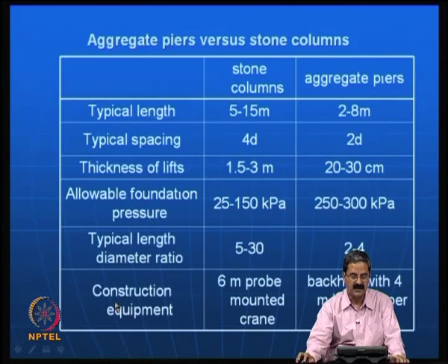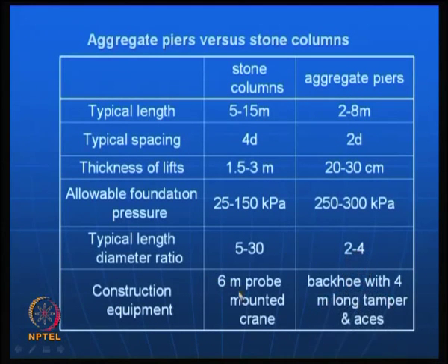And construction equipment, yes, I mean little probes and little more detailed, some even as I just mentioned, stone columns also could be conventional, in the sense you may not need high equipment, but nowadays very good companies are going for real time monitoring. As you construct, I should know exactly how much stone is inside, and then you come back and make about 2 meters of stone column and immediately run that static cone penetration test, check if that SPT value or CPT value is all right. People have been doing like that.